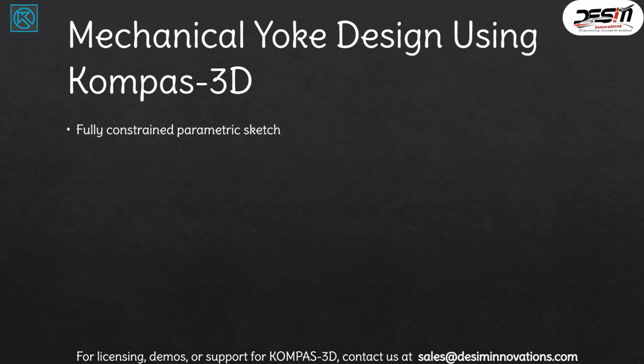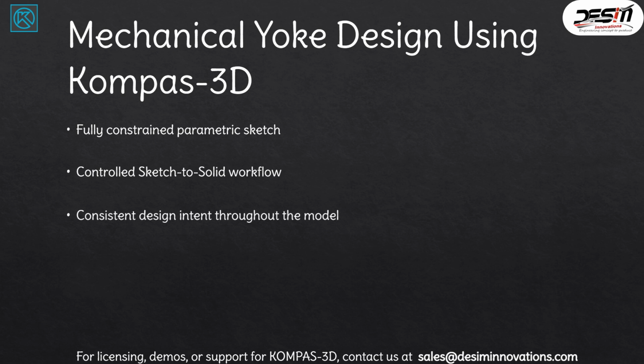We start with a controlled 2D sketch, where every dimension and constraint is intentionally defined. This ensures the model stays stable and easy to modify at any stage. From there, we convert the sketch into a 3D solid using a structured, feature-based workflow. Geometric relationships are carefully applied to maintain design intent and mechanical accuracy throughout the modeling process. The focus here is not just creating geometry, but creating controlled, engineering-ready geometry.